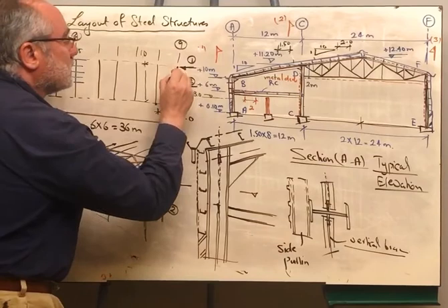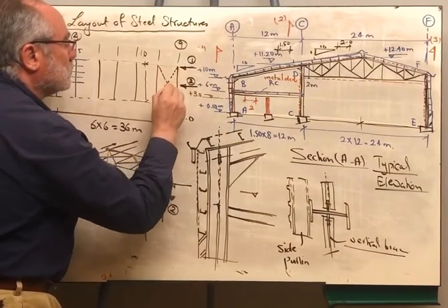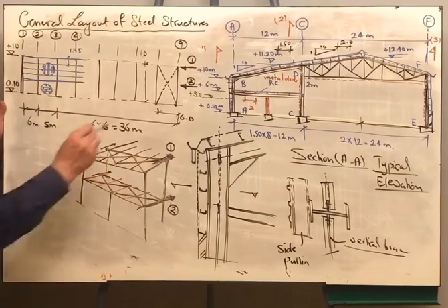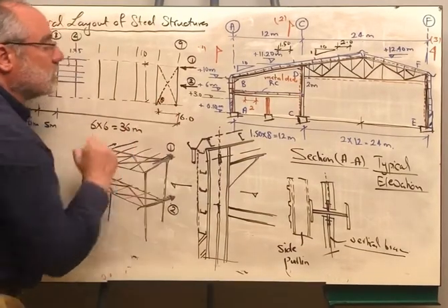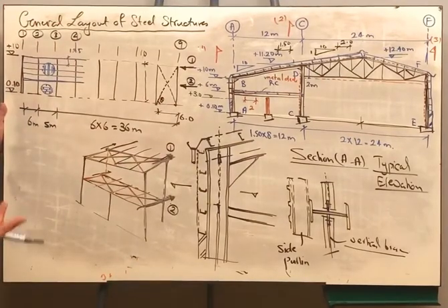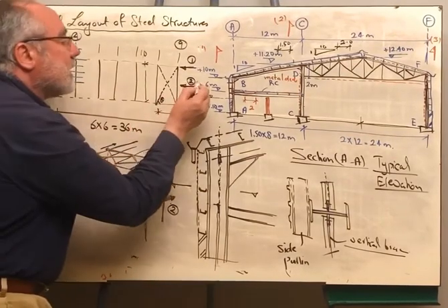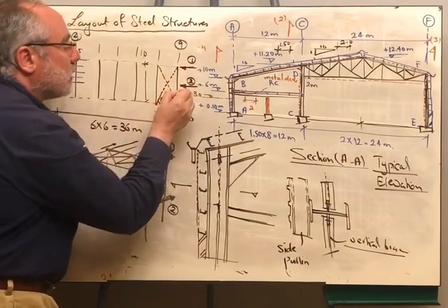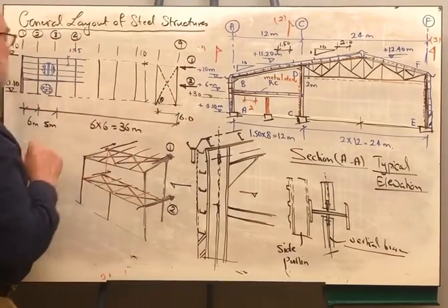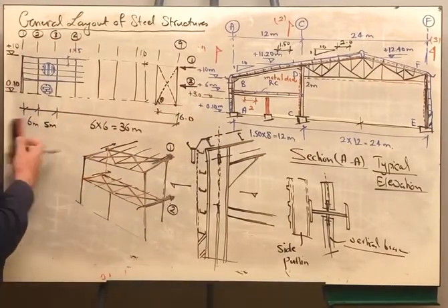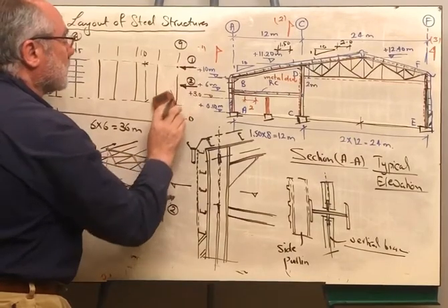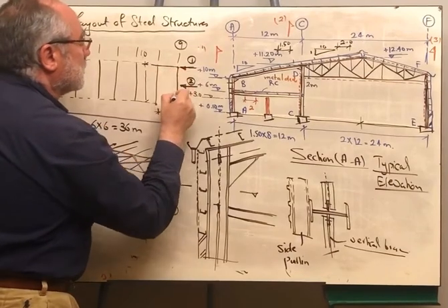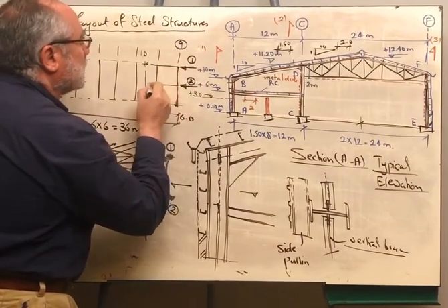Again, one student might think that he or she will do a system like this. This is wrong, although the angle theta is between 30 and 60. What's wrong about it? It did not respect force 2. Whenever you are having a force, you cannot have a force applied in the middle of a member. There should be a joint. Therefore, here I should have a member, and here I should have a member.